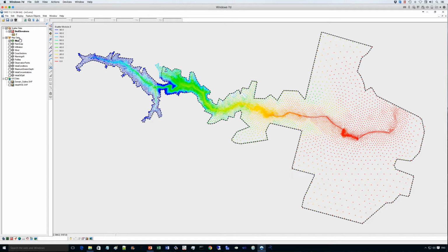whole file. And what I need to do is just generate the mesh. Oh, I'm missing something, sorry. I need a boundary condition downstream. Let me leave it this way. I will leave it close, so the water will get to this boundary and stop there. But there is a way to define the downstream boundary condition as open. But just for the sake of saving a little time, I will leave it that way. So let me generate the mesh using the feature object map to 2D mesh command.